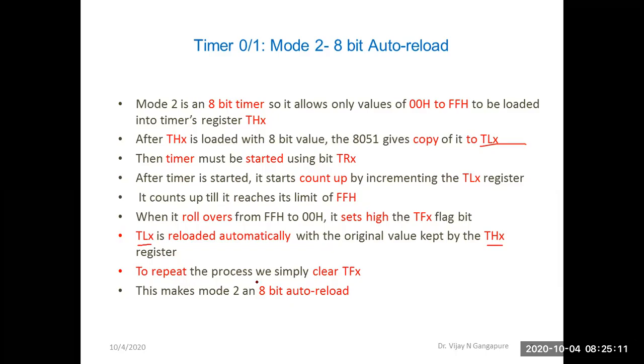To repeat the process, we have to simply clear TFX. Now see the difference. There is no need to stop the timer. We only have to clear the TFX bit, because that initial count value is already automatically loaded into TLX. So to repeat this timer, meaning to generate the same amount of delay, we have to just clear the TFX flag bit. So this makes mode 2 an 8-bit auto reload mode.